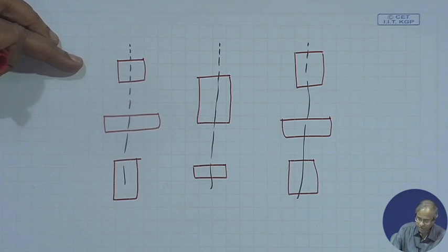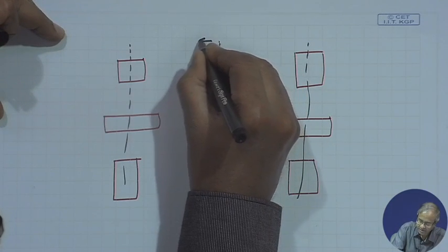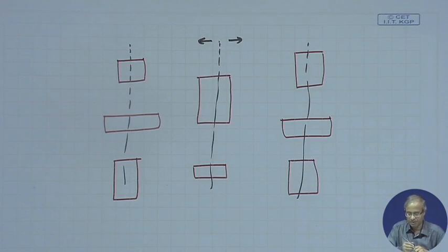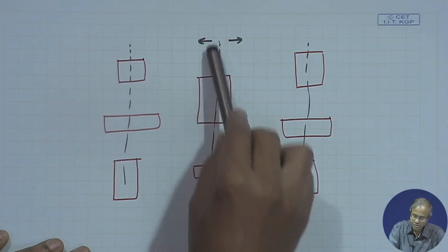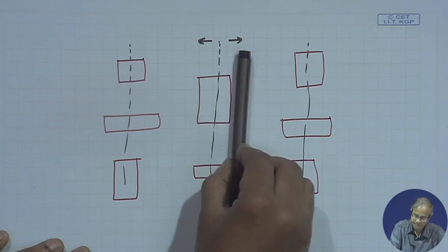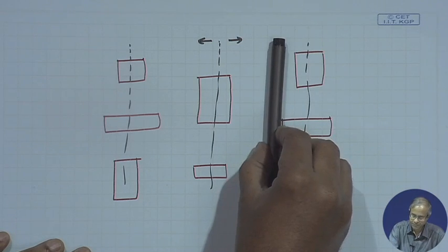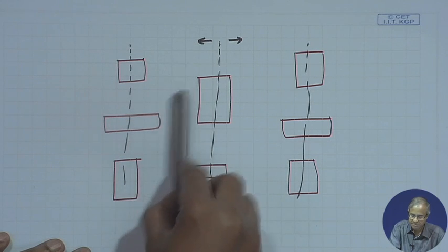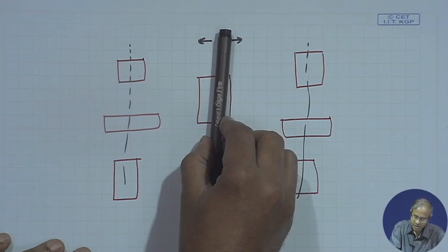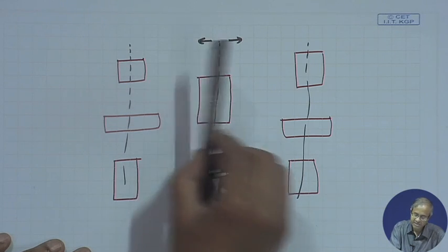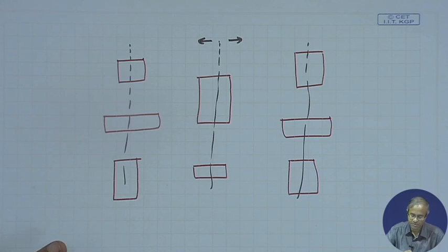Right. So, here what I am saying is that we are allowed to move these grid lines to the left or to the right, whatever is applicable, but when you move it, all the objects which are attached to the grid will all move simultaneously. This grid line, if you move to the left, all these 3 blocks will also move. So, you look at this separation, the minimum separation, and see whether the separation is greater than the minimum permissible. If not, you move it as long as there is no design rule violation. As soon as there is a violation, you stop there. Okay.